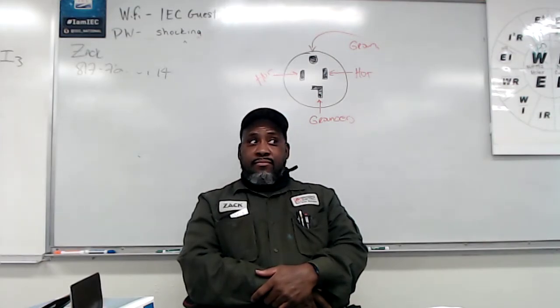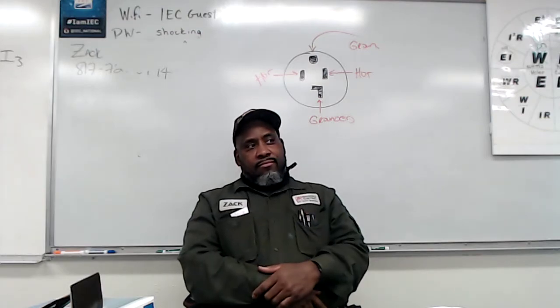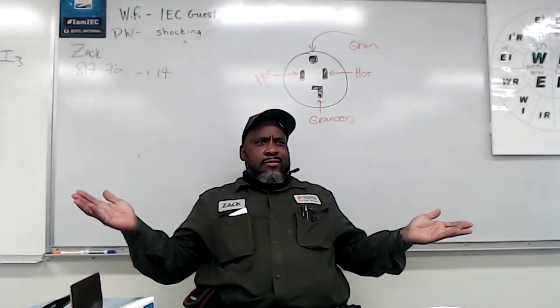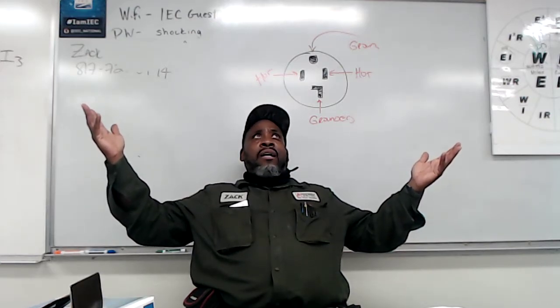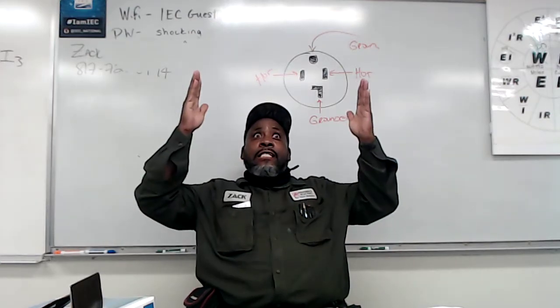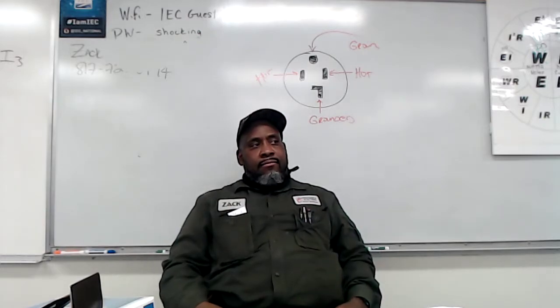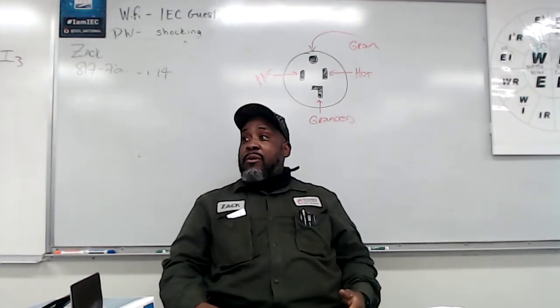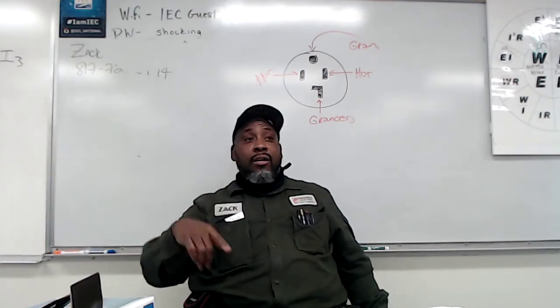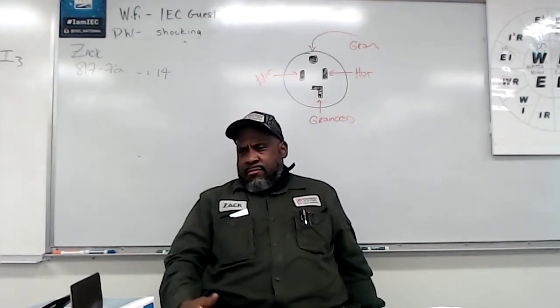That's why I was asking you if each light, since it's fed by the same circuit, matters. Each light. It doesn't matter. I got all these lights fed by the same circuit. But I still got to count what? Each light. I got to know how many watts each light carries to determine if that switch right there is going to hold all these lights. Don't I? It's the same.